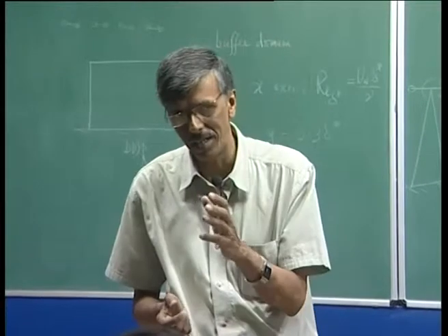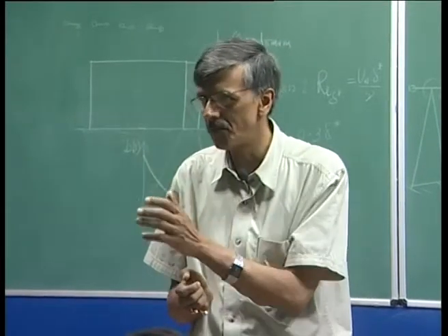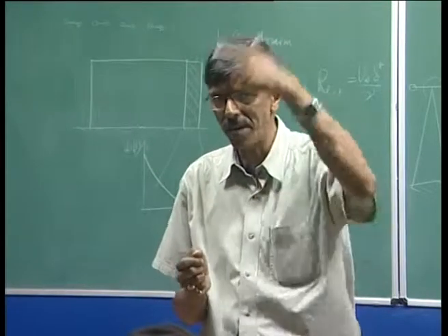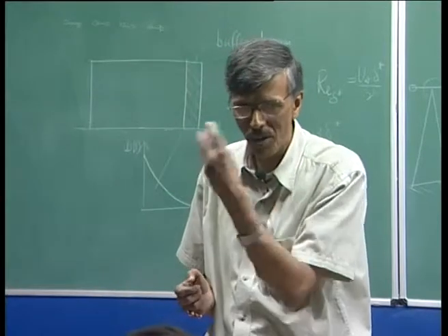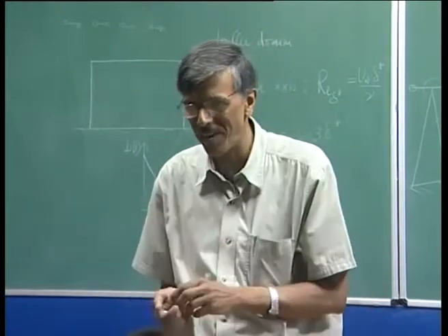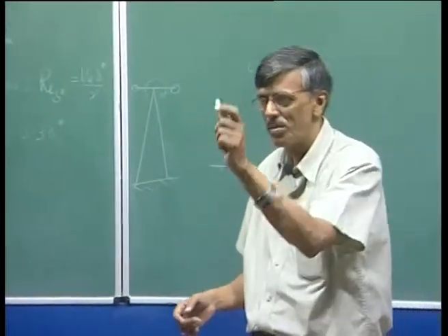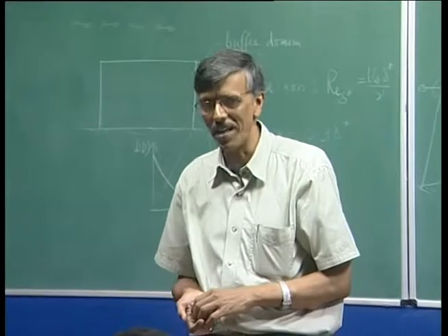But if you look at the compressor part and the stator behind a rotor, the rotor is rotating, so it is going to give out periodic vortices, exactly the same kind of thing. Instead of a flat plate, you should be talking about a compressor blade and vortices going there.